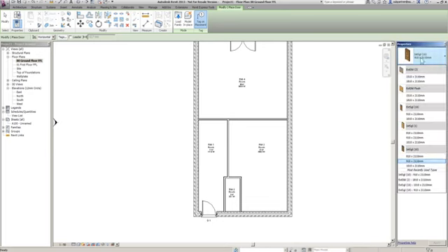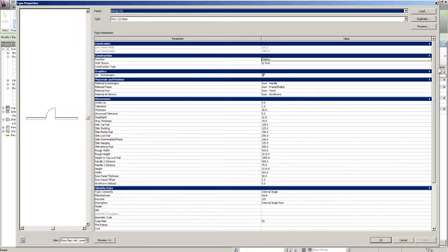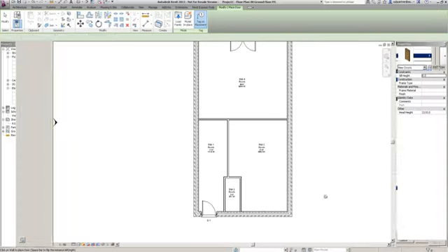Okay, there we go. Now, I'm going to put some 910 doors in. These work quite nice with the metric door openings, because if I go edit style, edit type up here, if we look at the 910, this is a structural opening. It gives you a door panel of 826, which obviously, as people in construction know, that's a metric door. I quite like that. It's got the tolerances outside of the frame, in the frame between the panels, and then obviously the frame sizes and all of that collaboration, so it works quite nice.